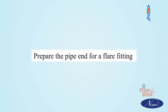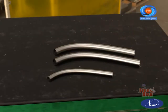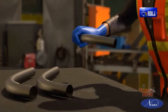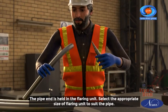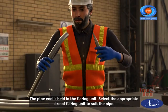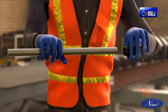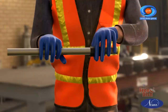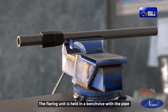Prepare the pipe end for a flare fitting. Flaring with block and punch tool. A pipe which is cleaned of burrs and bent should be selected. The pipe end is held in the flaring unit. Select the appropriate size of flaring unit to suit the pipe. Sleeve and cap nut should be assembled before flaring. The flaring unit is held in a bench vise with the pipe.